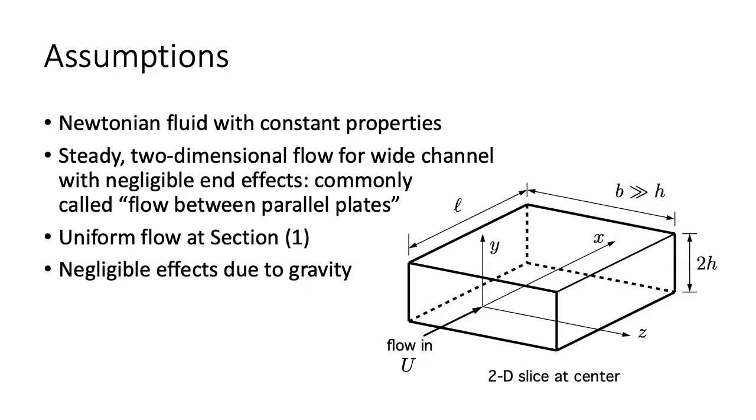Also, note that for the flow at the outlet, the velocity only depends on the y direction. Thus, it is now one-dimensional. This is called fully developed flow. However, to get to this profile, it needed to go to 0 at the walls by the no-slip condition, while speeding up in the center, which requires that the flow be two-dimensional. This is called the entry region.